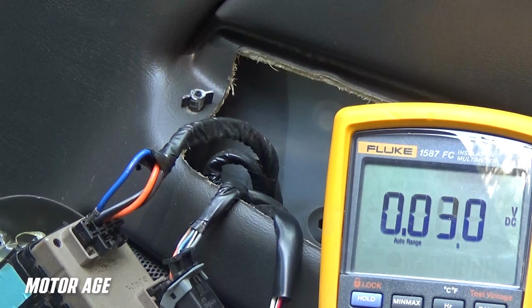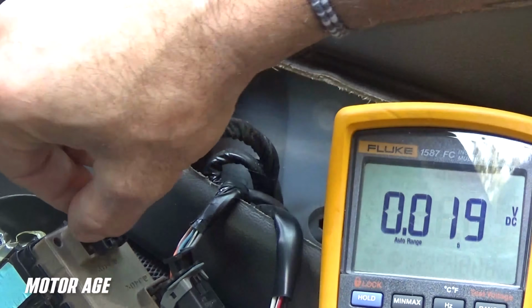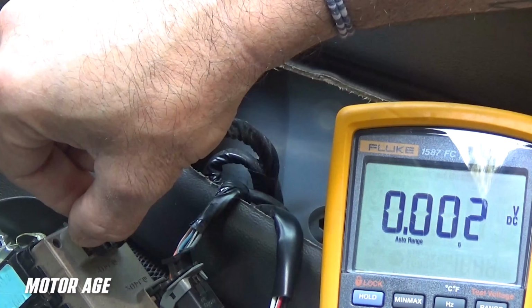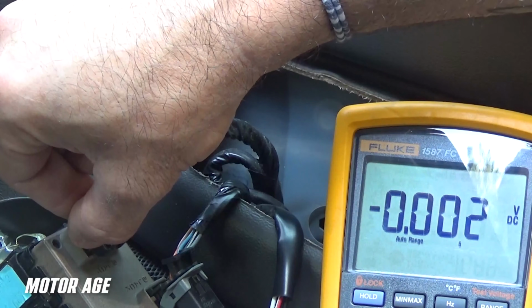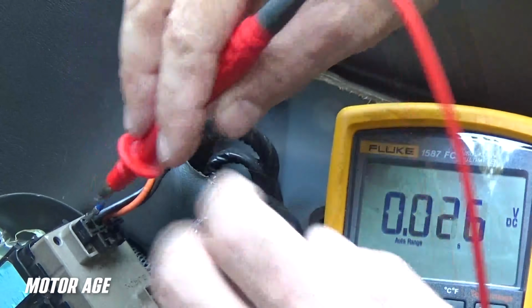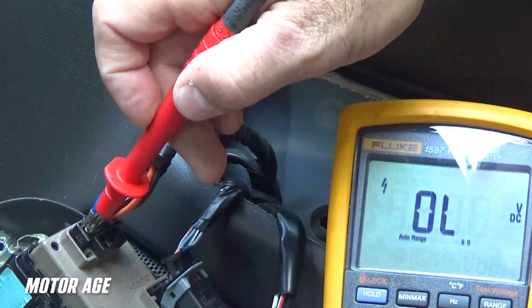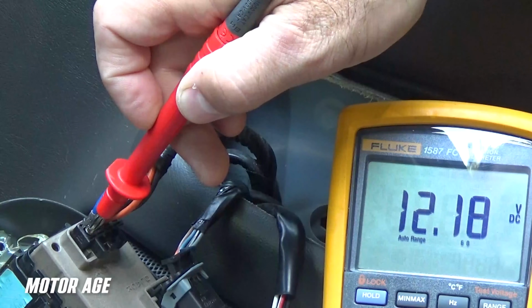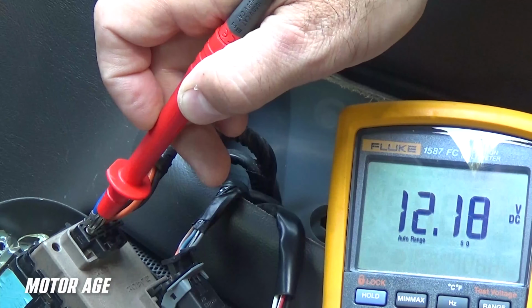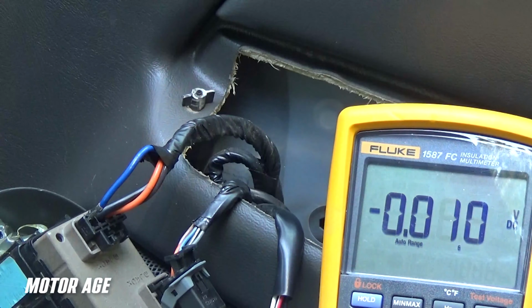Before I take the door panel apart and make my way back to the motor, I can do another test to help infer what's going on. I'm going to now go on the blue wire. The brown wire feeds voltage to the motor, and it's this blue wire that carries that voltage back to ground, allowing the motor to operate. That should be at 0 volts when I push the down button. And it is at 12 volts, indicating we have lost the ground path. But what it also indicates is that we have continuity through the motor.